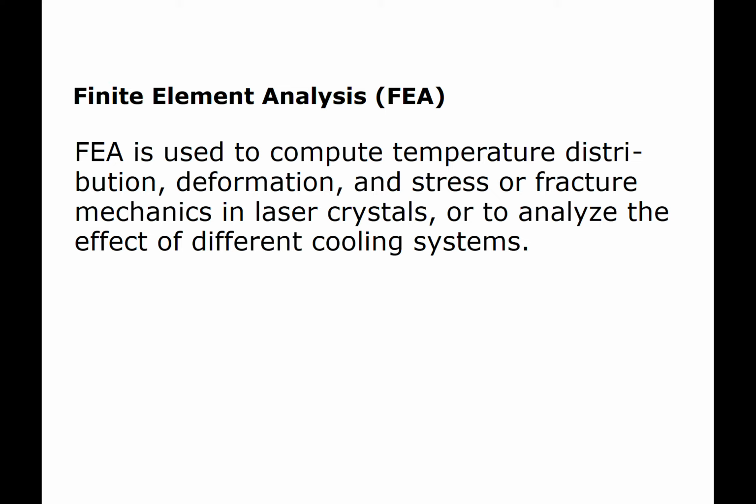So basically you generate heat by the lasers all the time, and as heat accumulates, the temperature goes up. And then this will change the whole story. For instance, the gain and absorption. And then the laser output is going to be a function of time, which is not desirable, so what they have done is to try to stabilize the thermal effect by cooling.